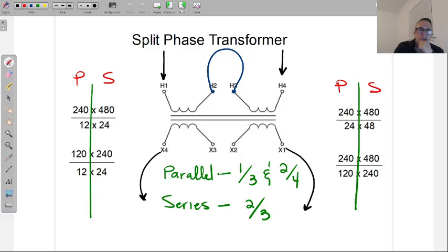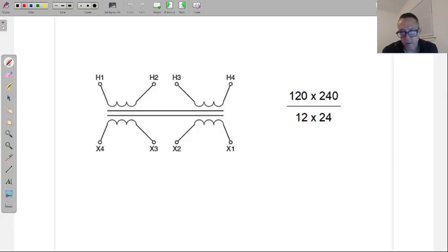All right, so now that we have the notes, let's start to piece this together individually. Say we're working with this transformer. The one we're working with is 120 or 240 on the primary side, and on the secondary side, I can get 12 or I can get 24. I can't get both, and I cannot connect both voltages to the primary. It's either one or the other. Plugging it into an outlet that's 120 or connecting it to something that's 240, either one is fine, so whatever's available is good.